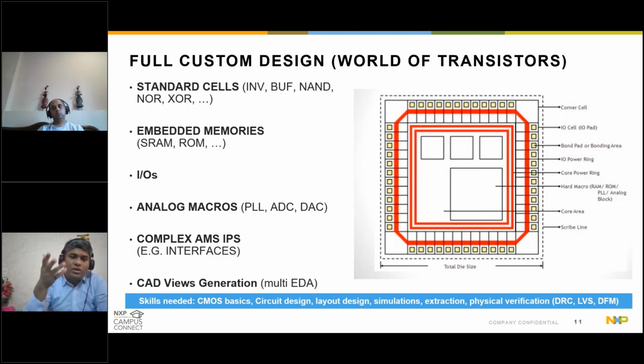That is the discipline where the challenges from a design side will come for you as engineers to solve. Or IOs, where you are basically marrying the macroscopic world to the microscopic world. How do you translate a high voltage domain into a more microelectronic domain? The transition between the macro world and the micro world essentially happens through the IO interfaces. That itself will have some elements of ESD, latch-up, and some element of analog as well, which needs to go into this kind of IO cell design.